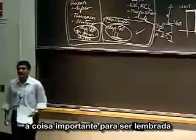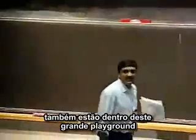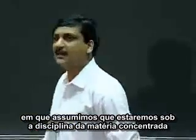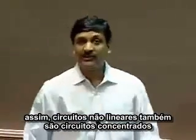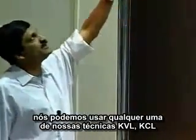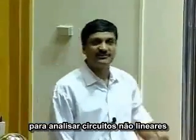The important thing to remember is that nonlinear circuits are also within this big playground in which we are going under the lumped matter discipline. Okay? So nonlinear circuits are also lumped circuits, and therefore, because we are in that playground, we can use any one of our techniques, KVL, KCL, or the node method, to analyze the nonlinear circuits.